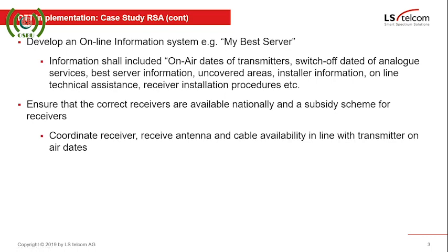Then apart from that, it's not only the receivers, it's also the receive antennas. You will find many receive antennas being distributed, saying they are adequate to receive the program. But what one needs to look at, when you do your planning, you will focus and have your coverage design based on a typical receive antenna with a certain number of dBs of gain. You will also make sure that you use cables that haven't got too much cable loss.